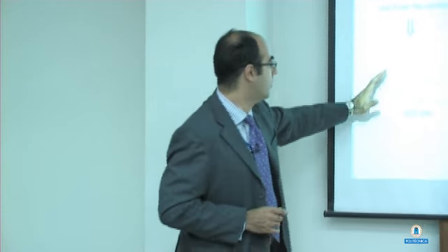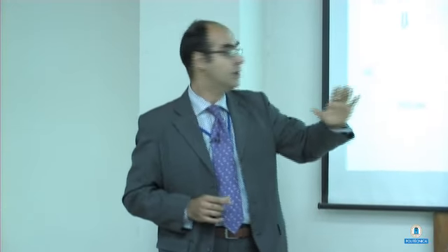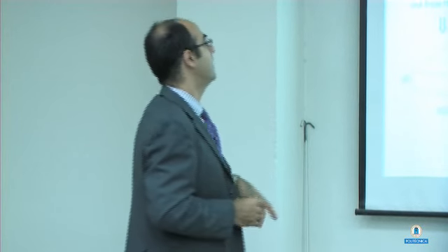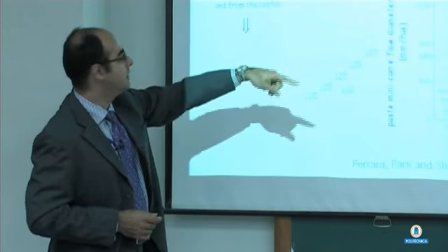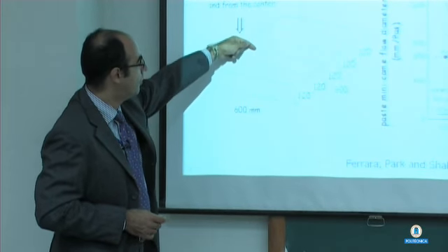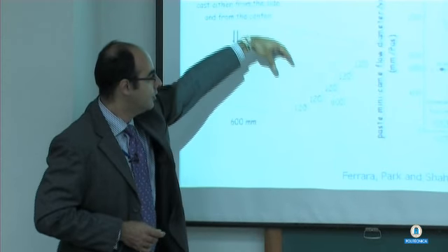We used fibers 35 millimeters long, so there was surely a tendency to lie in the plane, and we neglected the true thickness measurements because the thickness was quite small compared to the length of the fibers. We cast 3 slabs with self-consolidating and segregating concrete, and we cast 2 from one side and the concrete flowed in this direction, while 1 was cast from the center with an umbrella flow of concrete from the center. While for the vibrated concrete, we put the concrete in the center and we vibrated it for a couple of minutes until the complete filling.